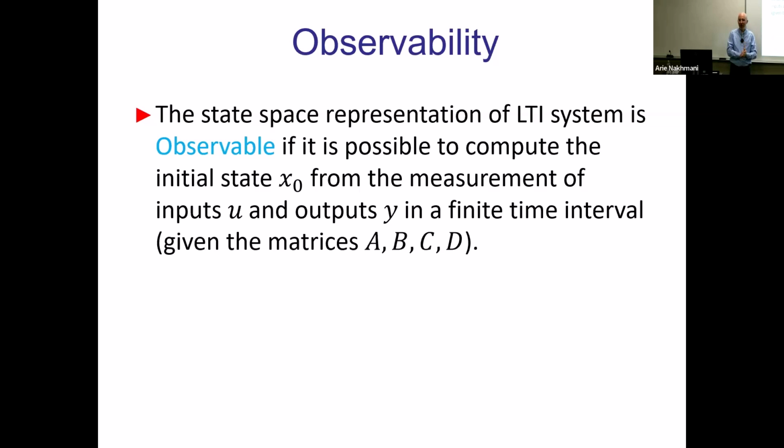This is the problem that we are trying to solve in observers in general. And the observability property means, if the system is observable, yes, you can, practically. You can take U and Y, and you can compute X from U and Y. And then that computed thing you can connect to the controller and return it back to the loop. This is how it works.